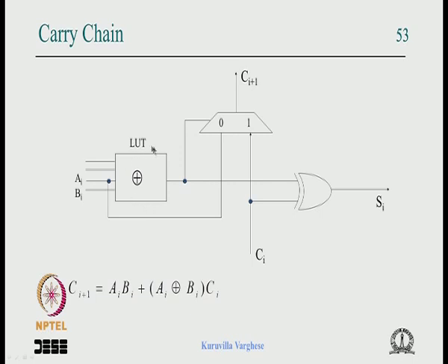Every lookup table you take will have a 2 to 1 mux connected, where the select line is connected to the output of the lookup table, and one of the 2 inputs comes from the previous section. The output of the mux goes to the input of the top mux, because this comes from the bottom and goes to the top.